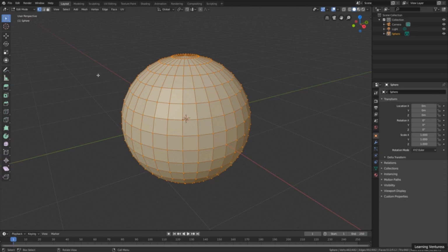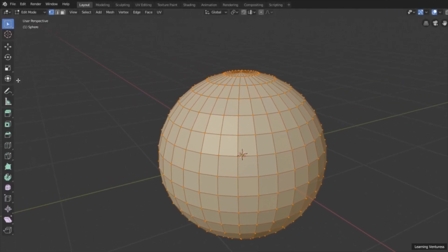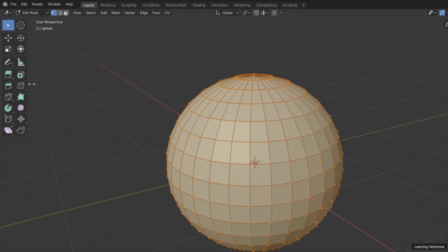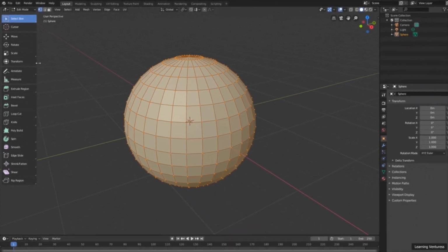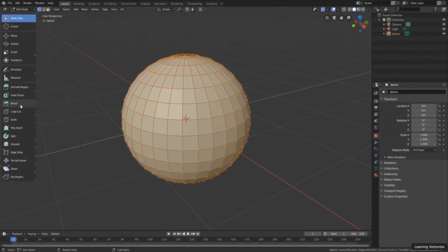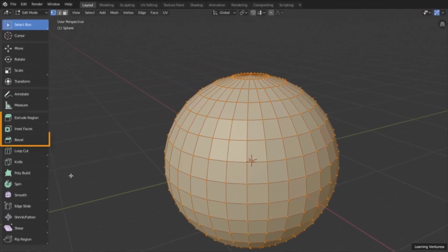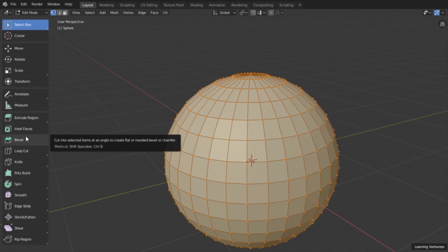I will click on the corner of the toolbar here on the right and drag to the center of the 3D view, so we can see the names of each button. The tool icons have a very good design, and when you know each of them, you can easily identify each tool by just looking at the icon. But while we are learning, it may be a good idea to make the names visible until we get used to the icons. In this lesson, we will focus on these first 3 buttons of the Toolbar's Polygonal Modeling Tools group: the Extrude, the Inset, and the Bevel.